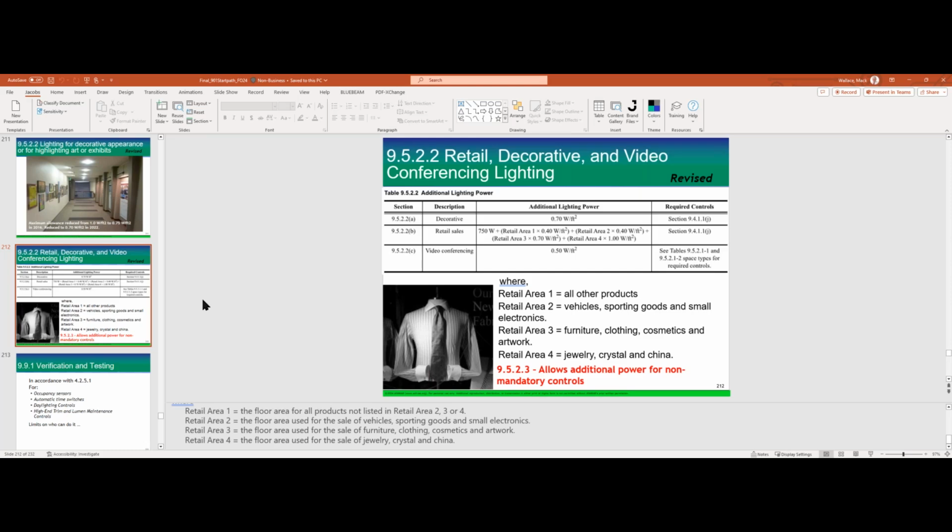My question is not about the square footage, how to determine the square footage. It's about can we use that additional credit for other places? Like when you do calculation, for example, if I have retail space and I have office, can I trade off the lighting in the retail area? Based on the ASHRAE compliance form, then no, you have to be in the same space.